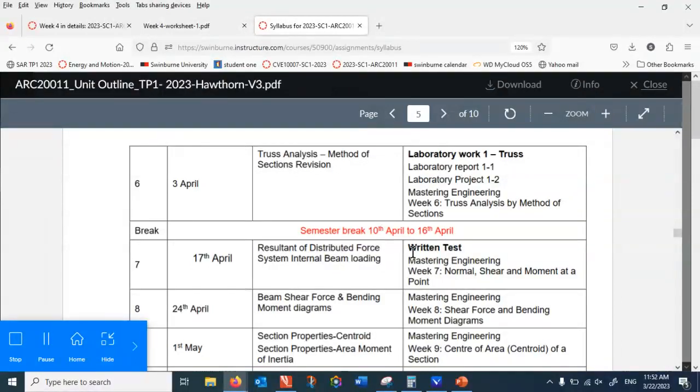You put together some truss structures like Lego, and then one member is magnetic. So the tensile member is magnetic. When you increase the load, the magnet would break. So you can measure how much that magnet can take. That's the strength of the member, and you do a calculation. This gives you a very close match, and believe me, that's something fun.